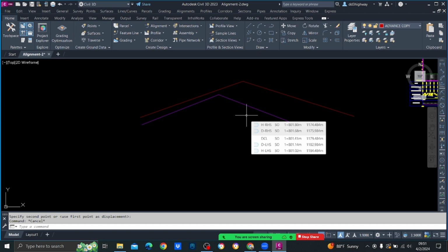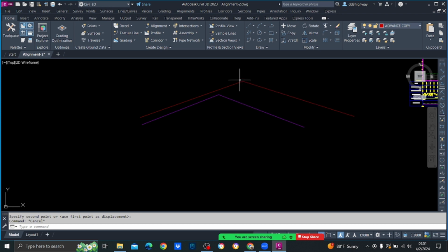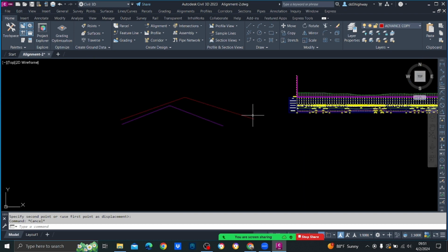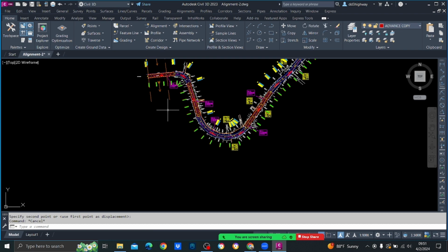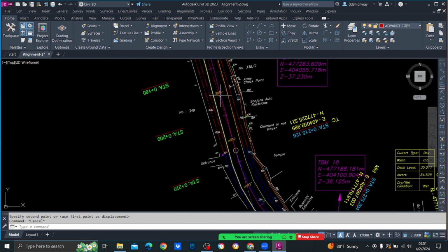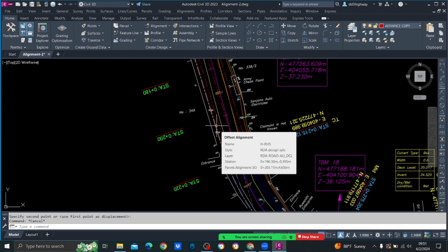That means we change the levels. Earlier it was somewhere here. Now we raised it. The center line level we raised is to match with the existing cross section. That is what we call recambering. So what we do is we are going to create a surface, ensuring that minimum thickness is there throughout the road, not only in the center line. Now do you understand?